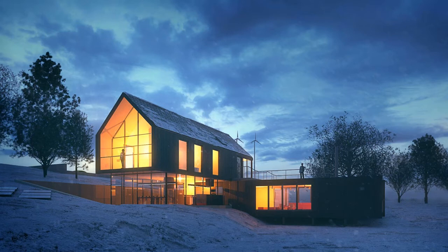The roof that you see there is again an override material that's rendered in this case in two passes. We've done a roof shingle and then we've done an override snow that's got some knockouts applied to it so that it appears as though snow is only placed in a few areas on the roof. So lots of little tweaking here and there. This image actually takes hours of compositing to put together, but with a little bit of effort you can get here fairly quickly, and it will give you some fantastic results that you can sit in front of a client.